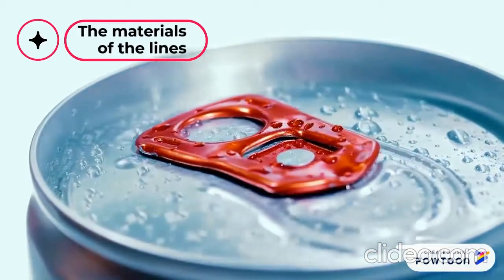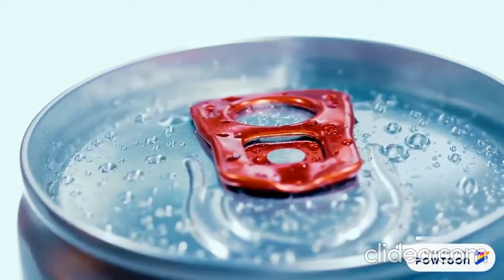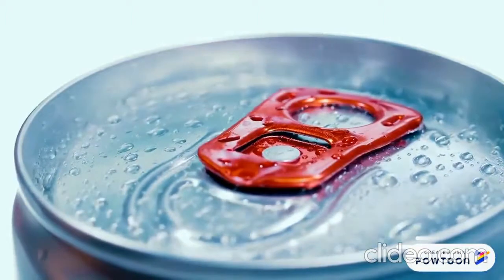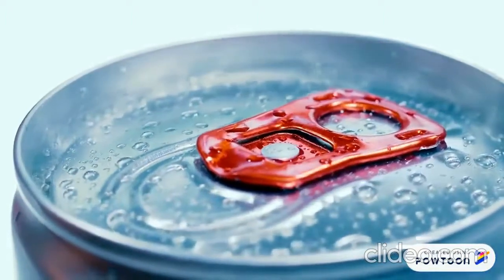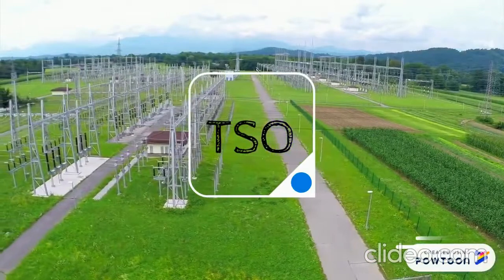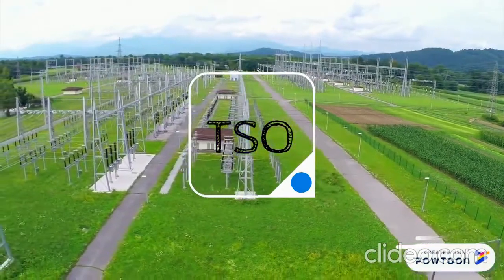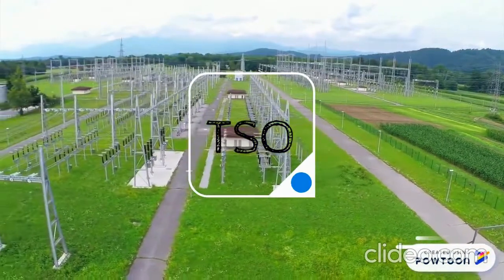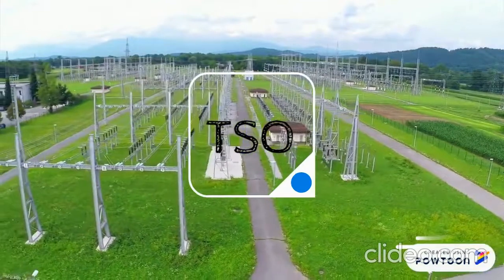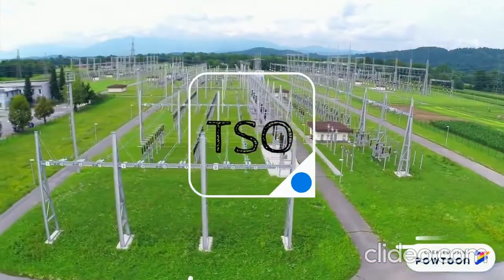This metal, despite being less conductive than copper, has a much lower density, which results in a lower weight in the lines and allows these enormous posts to be farther apart, cheapening the cost of the line. The transmission lines and substations are measured, operated, and protected by some groups called TSO, or Transmission System Operators, who act in real time to ensure their optimal working conditions. In Spain, the TSO is called REE, which stands for Red Eléctrica de España.